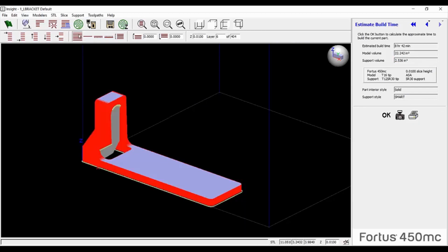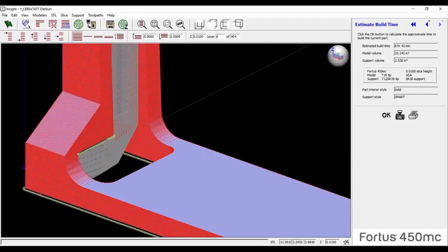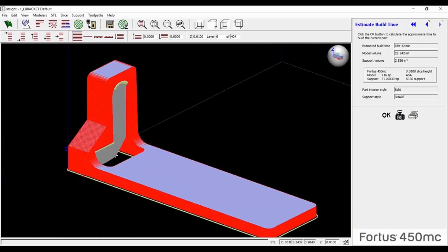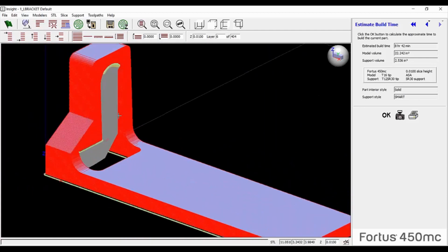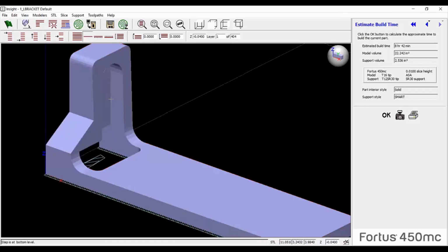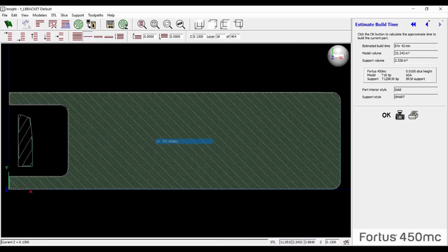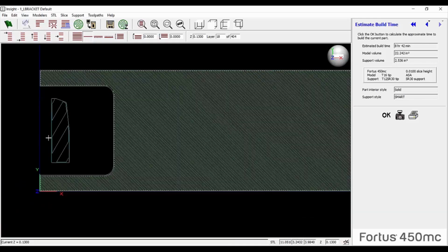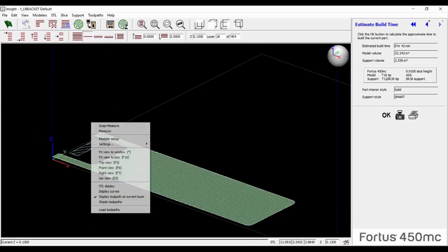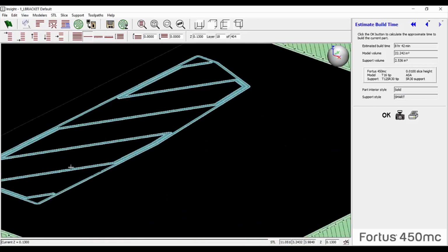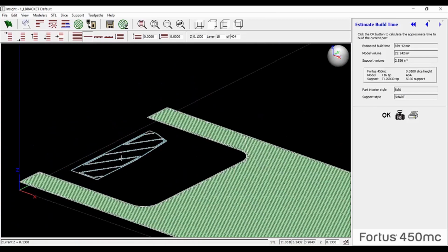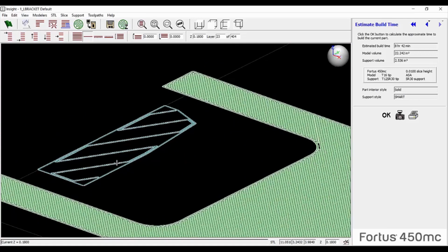So again, the first technique we're highlighting is: switch model material to support, switch support structures to model material. If I look at all of the layers in this part, you see that gray. The gray is what we call the support sparse group. It's a sparse filler region that is essentially just building up a scaffold for later use. If I turn off my STL display, right there we're looking at that sparse structure. And if I turn on my toolpath shading, we can see it a little more clearly. There's the support structure. If I pan through, this is just arbitrary scaffolding.